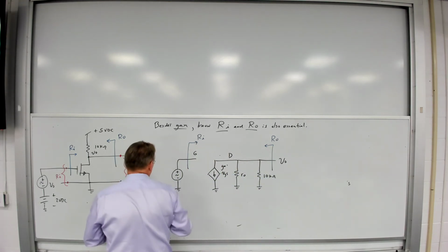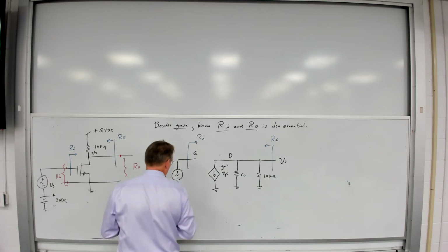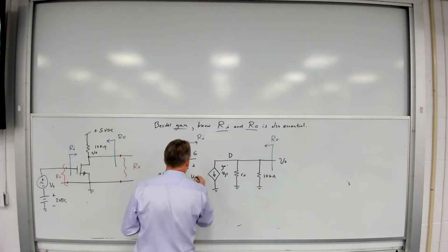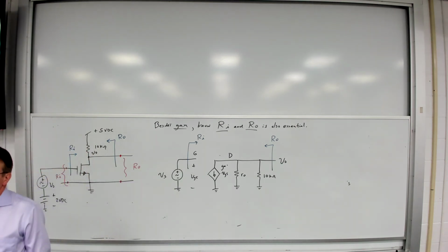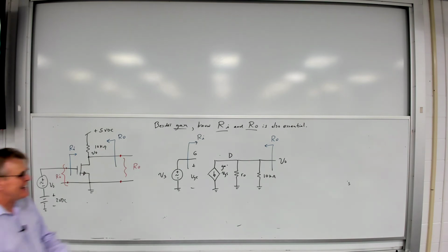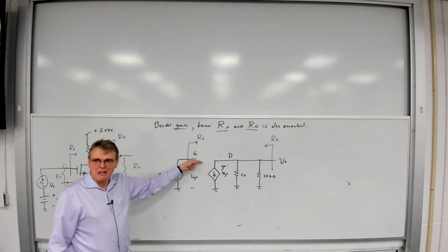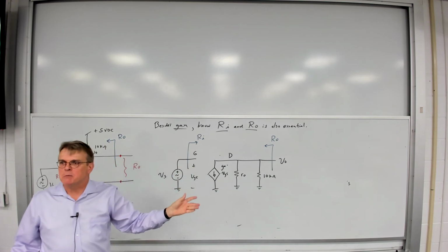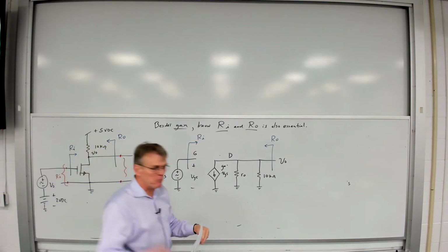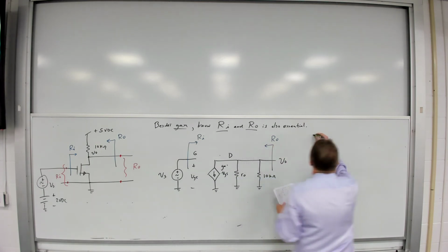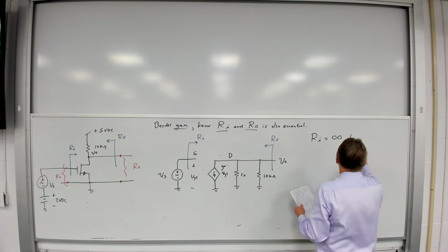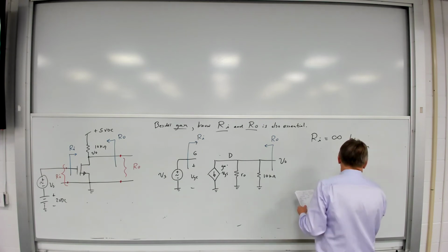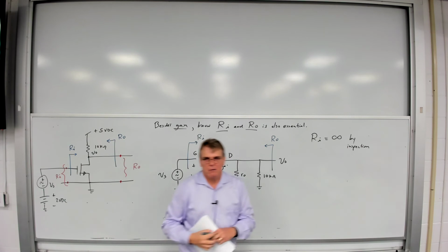And at least in one case, it's pretty straightforward. All right? What's the input resistance of this circuit? Infinity, by inspection, right? It's an open circuit looking into here. So R sub I by inspection is simply equal to infinity. This is a simple one, at least for the input. So that one is easy. You didn't really need Thevenin for that one. You could just tell by inspection.